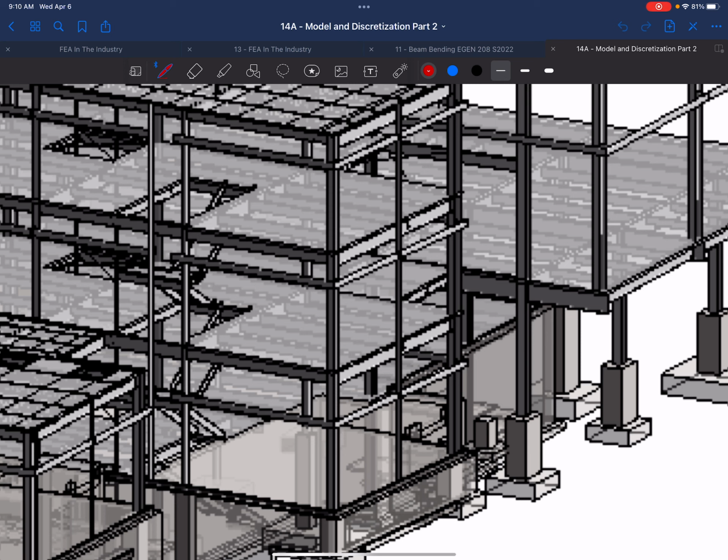It'd be interesting to see, now that you guys have some experience with MATLAB, what they're doing inside of VA. How do you take a beam, once you have the nodal reactions? Then they have to go through and use mechanics and calculate at all those little discrete points, like you did in your homework, what the internal forces are. Then they have to take those internal forces and relate them back to the AISC steel manual, and to all the checks in chapters E and F and G and everything else. What does that look like?